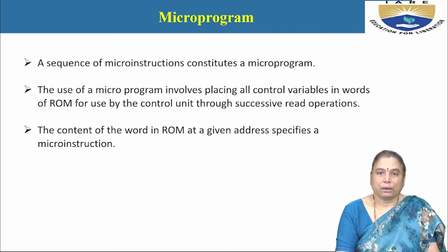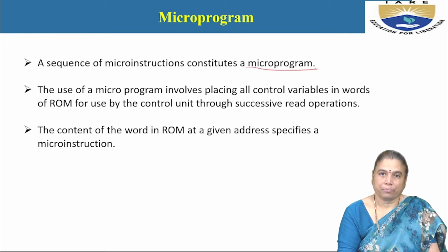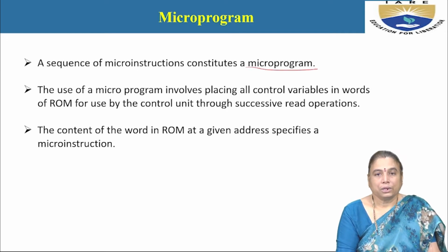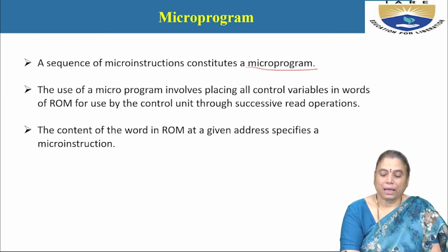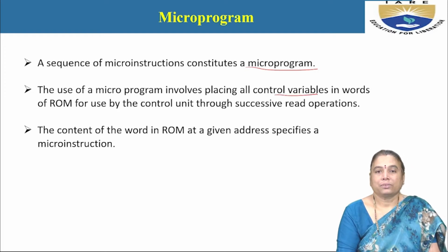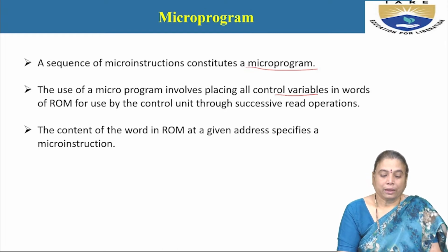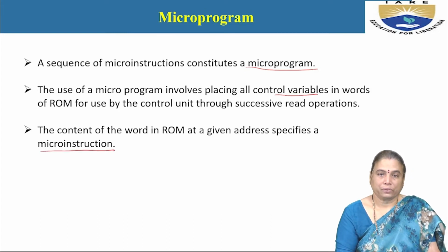What is a microprogram? A sequence of microinstructions constitutes a microprogram. The collection of microinstructions is a microprogram and can be executed one after another in a sequence. The use of a microprogram involves planning all control variables and how the task has to be performed. Those tasks have to be written in a sequence pattern. The content of the word in the RAM at a given address specifies the microinstruction.